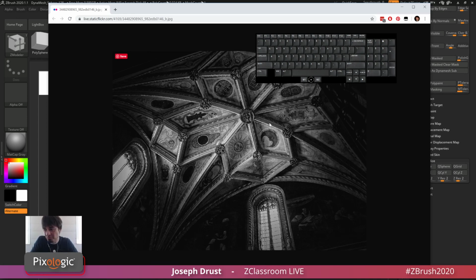Yeah, so for this one, what I would probably do is model your shapes and make each of these little star patterns your geometry, right? So this is a point, this is a point, this is a point, and all these are points. As long as your geometry when you're doing this is keeping it at a quad, which is 4 vertices, or a triangle, you're going to be okay.